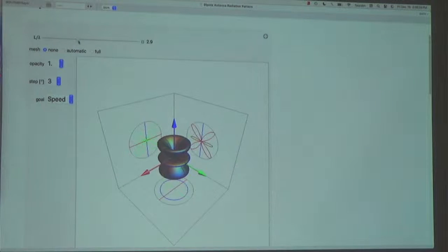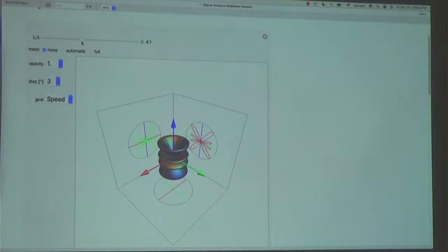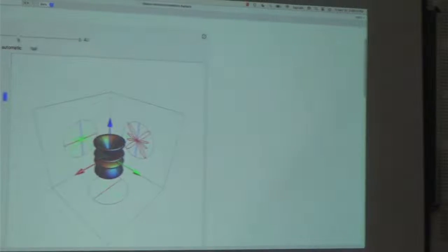Now you start seeing the problems. When you make it electrically very large, so we are talking about L by lambda of 4, which means if your wavelength is 3 meters, you're designing antennas that are 4 times that. With this you can see that azimuthal symmetry remains because there is no variation along that axis, but your elevation response has a lot of what we call lobes. Till now what you were looking at was just one single main lobe. But as you increase your length, when you sum the electric fields, now you have a huge phase variation along your dipole axis because your length is large.